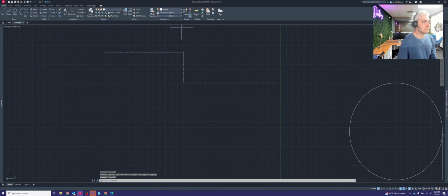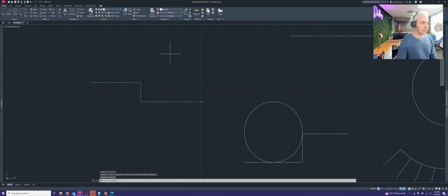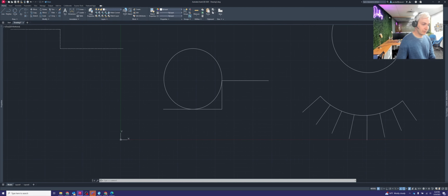All right. Also, there is groups too. So if you have a bunch of items that are all separate but in an area that you want to be grouped, like all these items here, I can go over to group, highlight this whole stack of items, hit enter, and then as I highlight that, all of those items are within a group. If you wanted to undo that, all you got to do is come up here next to where you have your group, and you can hit ungroup, and it will allow you to ungroup those items and go back to just having individual items up there.